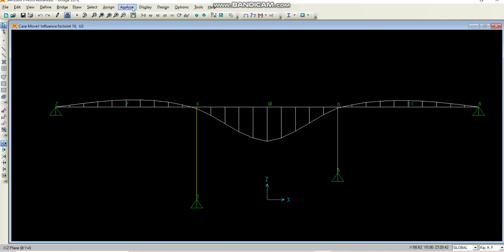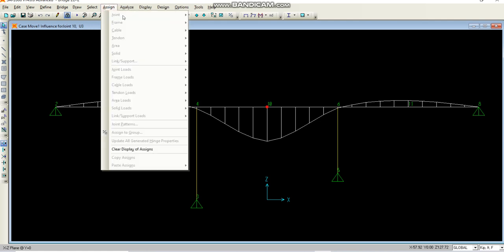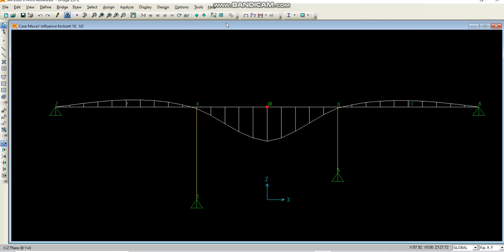influence line diagram. And please keep in mind that this influence line is constructed with three output stations. If you remember, in the assign, in the frame, we did something which we will do again. And these stations were specified for the girder objects, right? Now points for the influence line are calculated at each output station, and these points are then connected by straight lines, right? These are the straight lines.